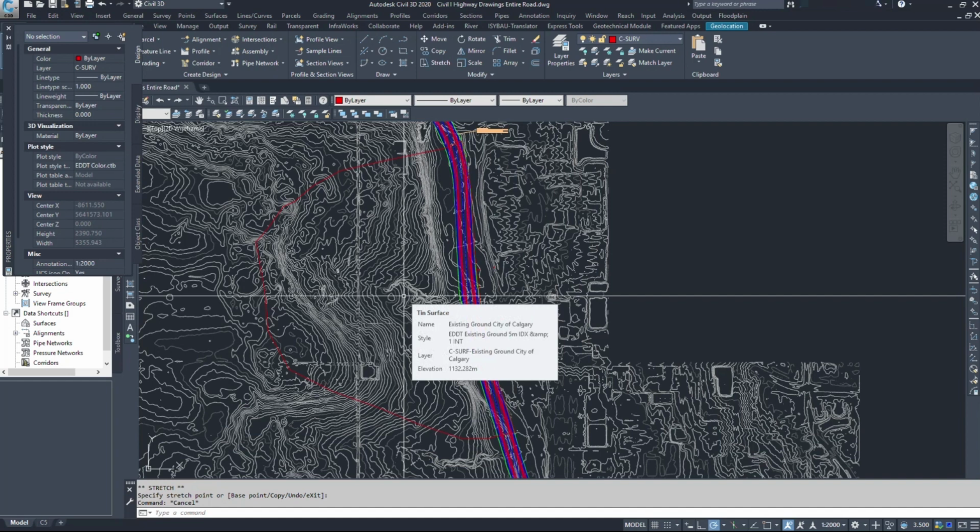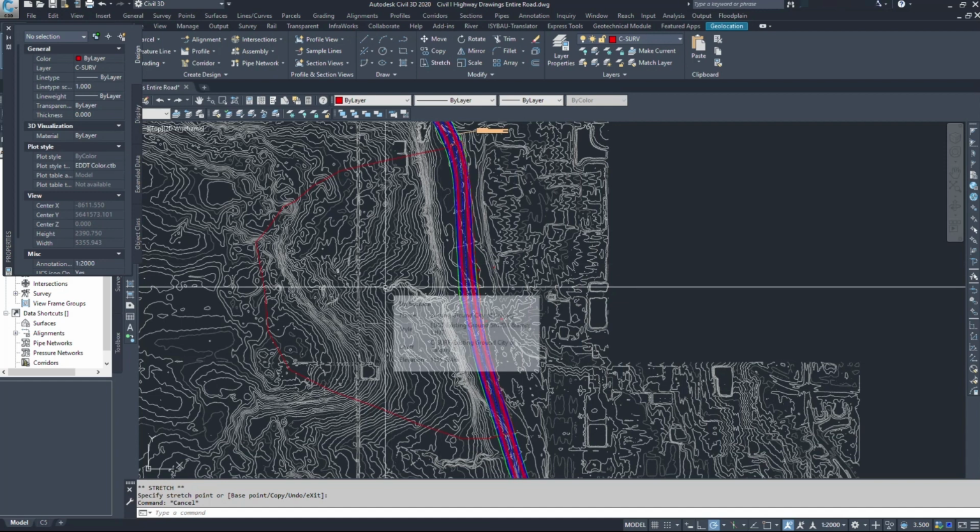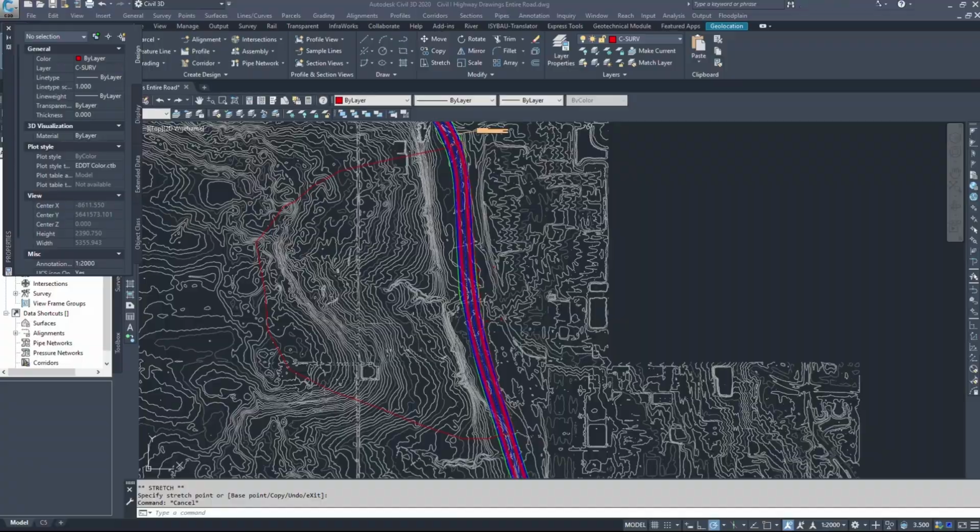So now that we have our area, we know where the water is going to flow, where the pond will be placed. We need to figure out how much rain is falling. Again, the City of Calgary does 70, 80, 90 liters per second per hectare. So we could figure that out based on the city requirements, or we could do the Government of Canada requirements.